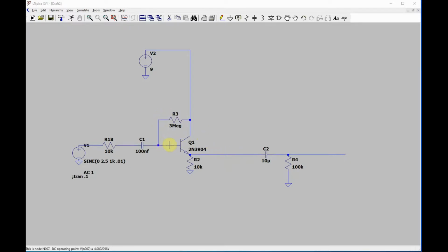Looking back, I'm using 10K here because this has zero source impedance. This 3 meg thing is also so large compared to this that you just use that. But the point is, you look backwards and you say, what's the impedance? Then you divide by the HFE and get that. But we're going to talk for a minute a little bit more about the output impedance of this and really how much current it can supply, because those are kind of two different questions, I'm told.